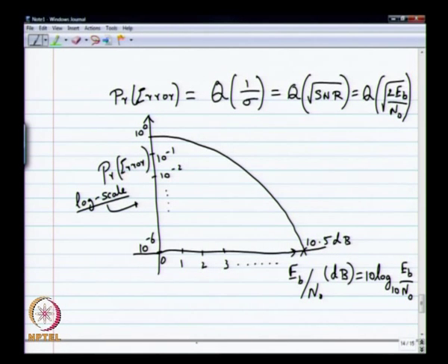So, once again let me remind you how to simulate it. Suppose I fix my Eb over N naught as 3 dB. How do I simulate this whole system? You have to compute sigma from 3 dB. BPSK Es has been fixed at plus 1 minus 1, so you have to compute sigma. For that it is a very simple formula. You go back to that formula and compute sigma, and then you know how to simulate the whole system. You run as many bits as necessary.